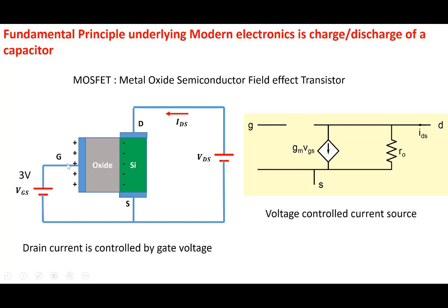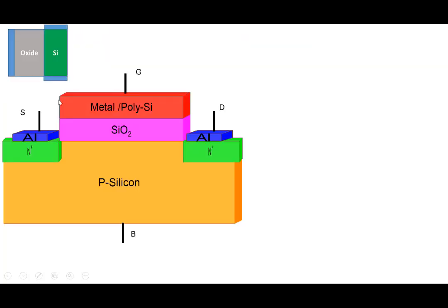So we are saying that the capacitive action, or a capacitor, is a fundamental part of a MOSFET. And this is the symbol that we use for a MOSFET, right? So gate here, and the gap between the two indicates the insulator here, and there's a drain and there's a source here. The arrow is used to differentiate between which one is source and which one is drain here. So it allows us to highlight that.